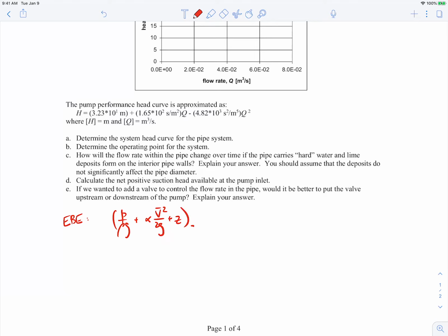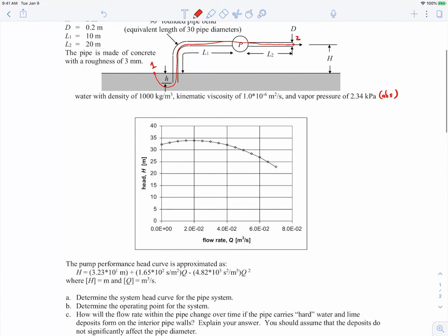Write down the whole equation. And let's go ahead and write down some of the things we know. We said that the pressures at 1 and 2 were both atmospheric pressure. We know the velocity at 1 was about equal to 0. Velocity at 2 was just equal to the velocity in the pipe. I'll just call it V bar for convenience. Let's put a coordinate system. We'll say that Z is just right there. So that Z1 is just 0, and Z2 is at capital H.